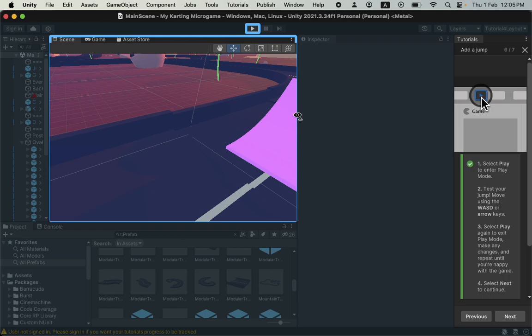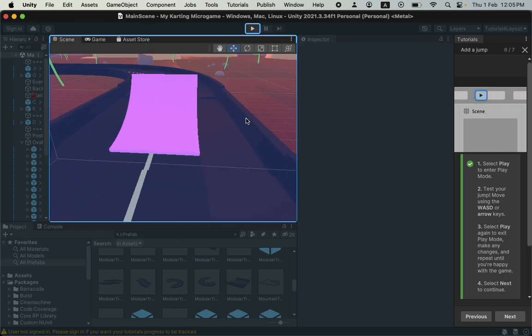So these two are the different kinds of rotations. If you want your camera to be at the center and the scene to move, you hold right click and move. If you want the scene to be at the center and the camera to move around the scene, imagine orbiting. Your camera is orbiting the scene. In that case, hold Alt key and left click and move around. So these two are the differences.